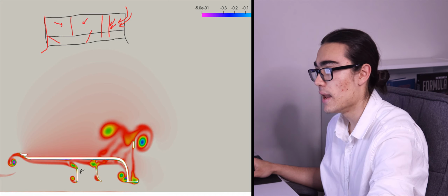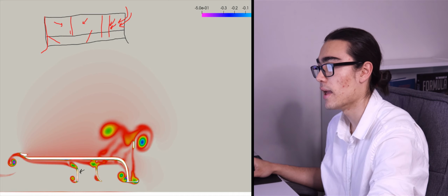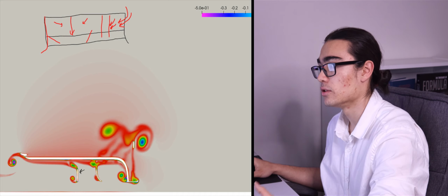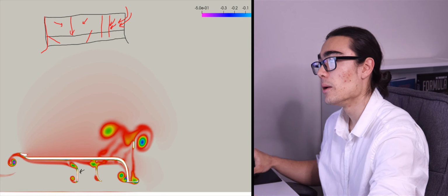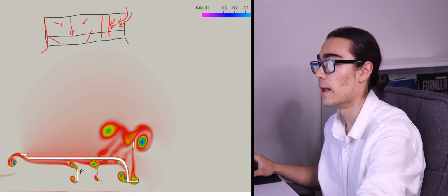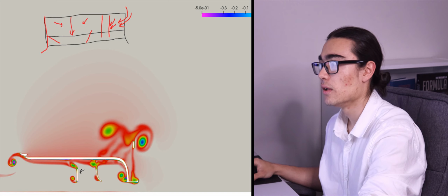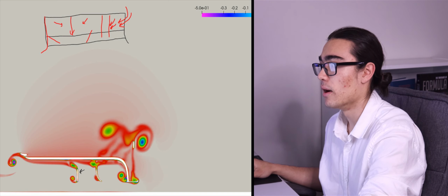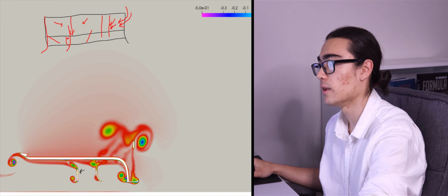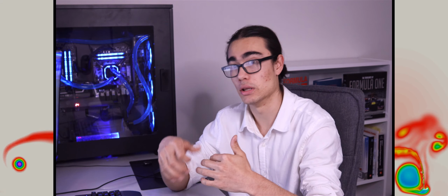So our net flow is going to be straight ahead. Or sorry, I should have said we might have flow coming from the outside, we might have flow coming from the inside, but we're in a much more balanced situation. So in this scenario, it might actually be more ideal to give our strakes a curve so that we can roll up a vortex off them, because we don't have that lateral inwash or potentially lateral outwash to play with to generate our vortices for us.